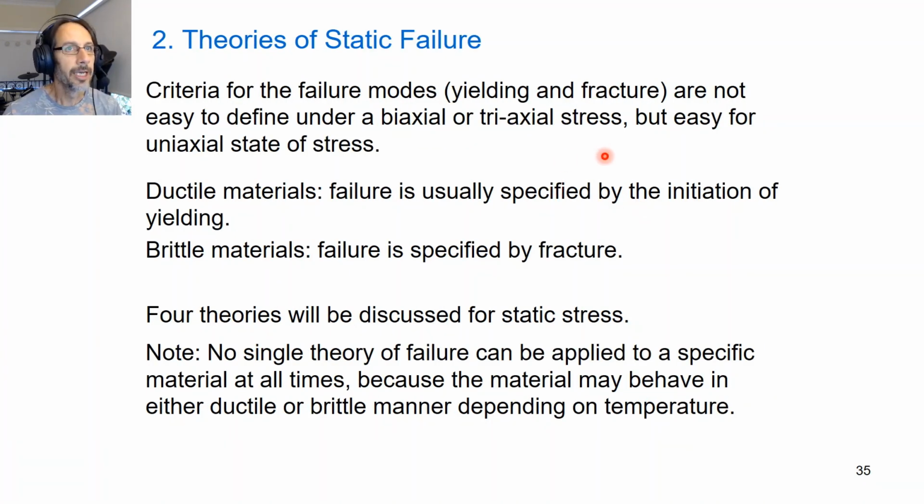Okay, so as I mentioned before, when you did something like this in mechanics of solids, or maybe even fundamentals of mechanical engineering, you may have calculated a stress and then just compared that directly with the yield stress or ultimate tensile stress of the material. That was okay then because you're looking at a simplified uniaxial state of stress. You may not have been told that at the time, but that's what you were doing.